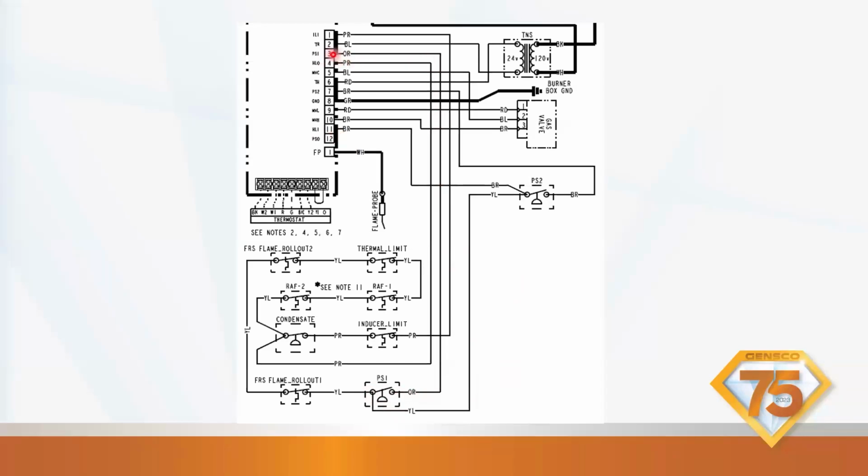PS1, or PSI, pressure switch in. And then you have PS2 on the brown wire when you go into high stage, PS2. So really simple. This is a ladder schematic, really easy to follow. Simple, you can see how it goes from switch to switch to switch to switch, and you can follow that power very easily. Problem is, that's not realistic.